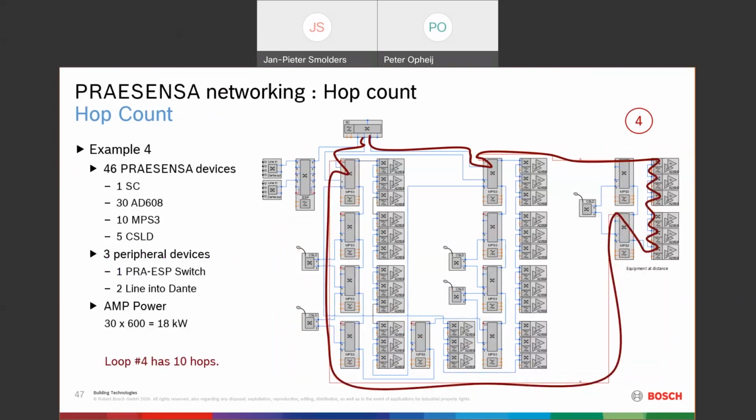That was everything I wanted to tell about RSTP and hop count. Those two things always go together. When you have switched on RSTP, and that's default in a PRAESENSA system, you always have to do your hop count. Don't forget. One thing that's important, if you have to do a design like this or even a bigger design, and you're not sure, send it to us. We can check it for you.